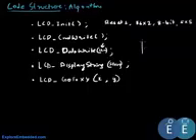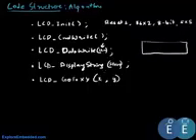Let me just draw it here. So this is x is 0 and this is 1, and this is y. y starts from 0 and ends at 15. With this command you can set the cursor to any position, like say this is 0 and 8. If you use lcd go to 0, 8, the cursor position goes here. And likewise there are commands to clear the display and all of that.